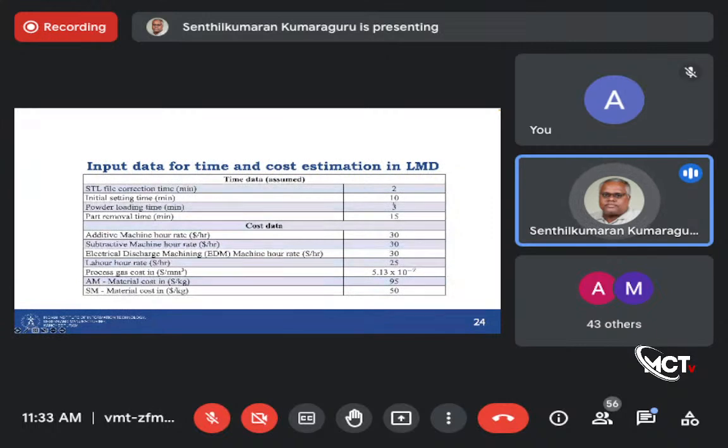So this is the time and cost estimation assumptions. This is the pre-processing time, and this is the cost-related data: what is the machine hour rate for LMD, what is the machine hour rate for CNC, and what is the electric discharge machine hour rate, and stuff like this. We have the cost of material, which is available in powder. Using powder is more expensive than stock like ingots, which is used for machining. Even the buy-to-fly ratio we can compare, but when you're using powders, it's slightly expensive because the production of the powder is away from your system boundary.